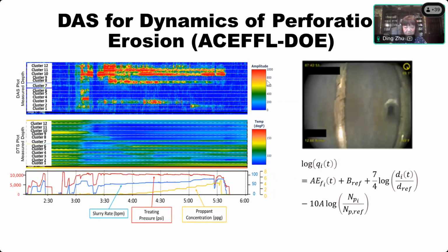Now with DUS measurement, to actually come up with uniformity, the design commonly used in US unconventional development is this perforation design called limited entry. So I actually perforate fewer holes or smaller holes. When the fluid goes through the perforation, it generates a pressure drop. Because the pressure drop restricts the fluid, that forces the fluid to go to the other perforation locations that were initially not receiving fluid. The limited entry design has been proven in the field, just by statistical observation, to actually work. And some operators say, I use the limited entry design, my production performance became better than not using it.